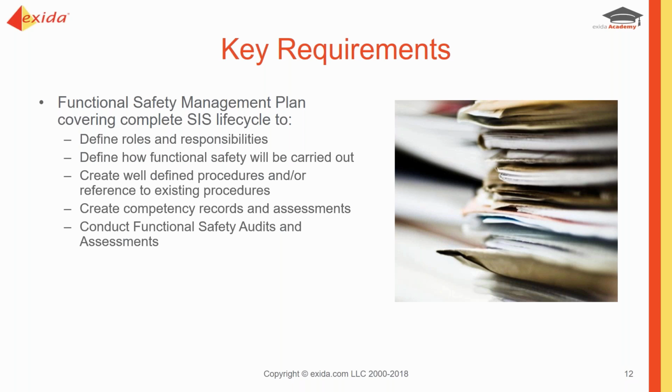And then conduct functional safety audits and assessments. So in this essence, the gap analysis would be the first functional safety audit. And that was where you can start. And then we need to make sure we're covering all the SIS design activities, not just the hardware design, but also the application software design. And we verify and validate the SIS design. So part of functional safety management is having procedures in place for being able to do this verification and validation.